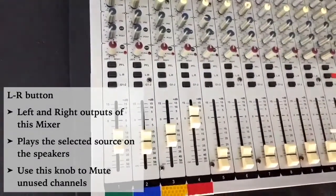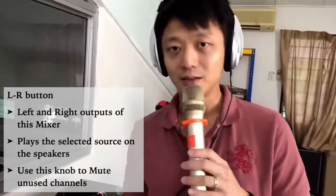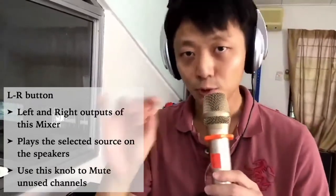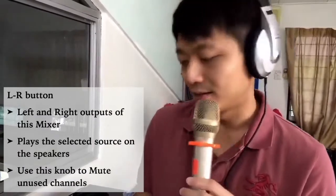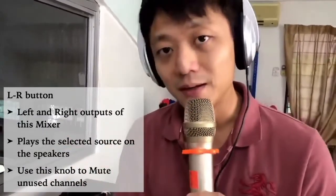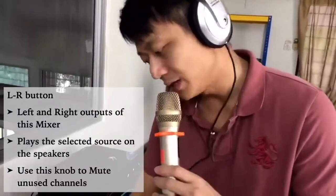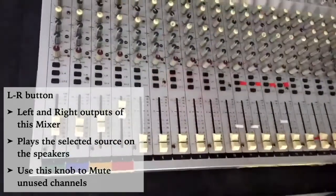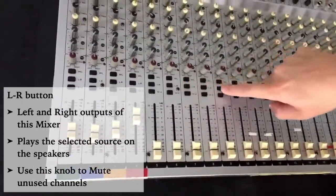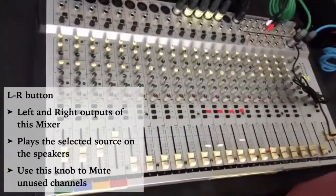That's why sometimes when everybody is singing, but they say nothing is coming out from the speakers, it could be because you did not select the LR button. The LR button can also be used as a mute button, and that's a very useful function. It is recommended that whatever sources are not used, you just turn off the LR. You don't want them to go into your final mix, because all these channels can carry some noise inside them, and you don't want them to interfere with your main audio output.